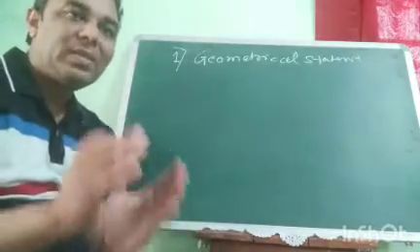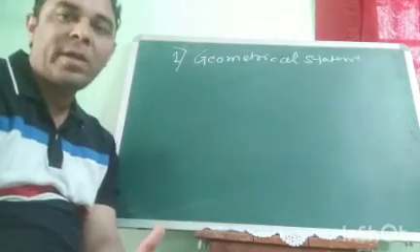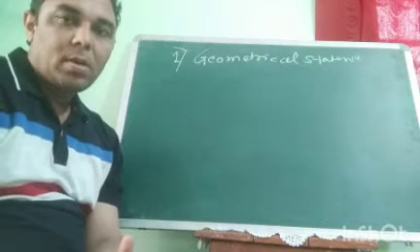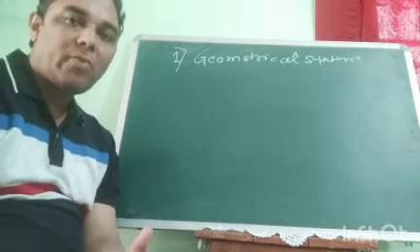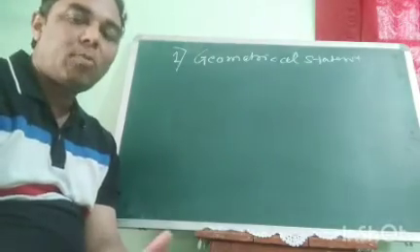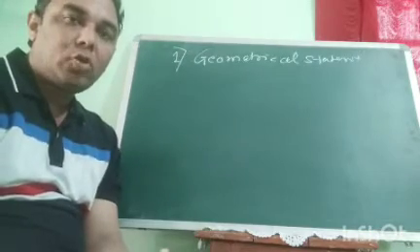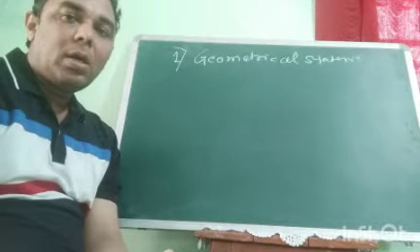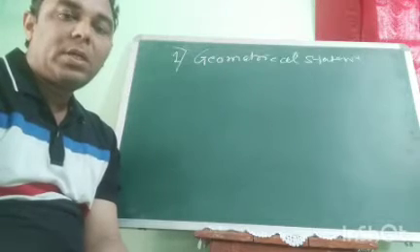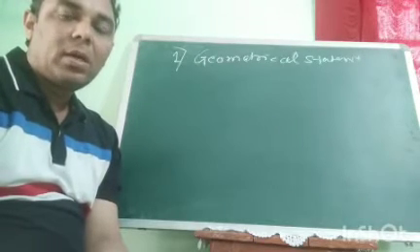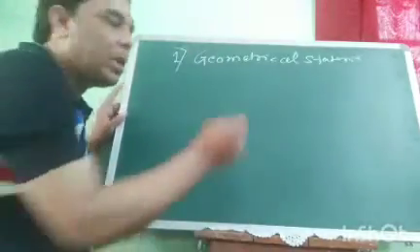So first of all, we need to study the design of a product: where the points are located, where the lines are located, where the planes are located. Getting me or not? Then we need to give the symbols of each geometrical entity in the form of points, lines, complete circle, ellipse, planes, and so on. So let's see how we can give the different symbols in APT part programming context, or we call it a syntax coding.